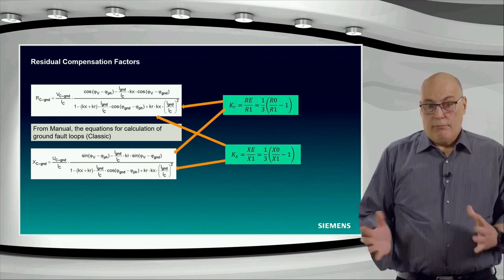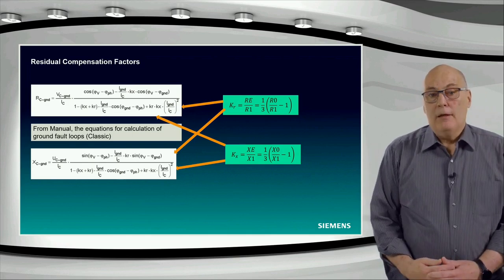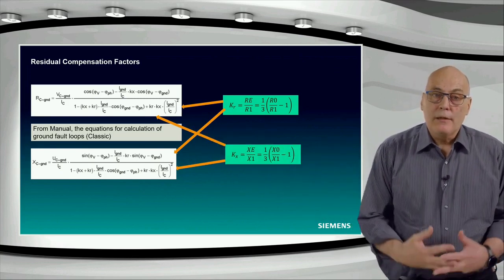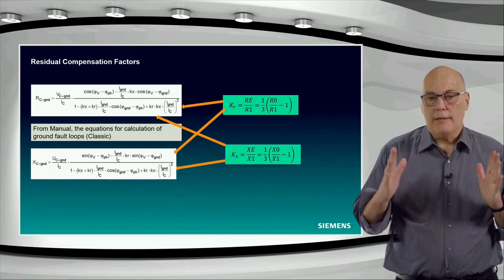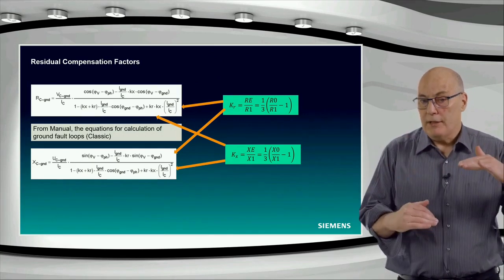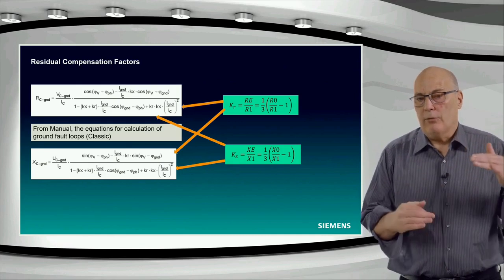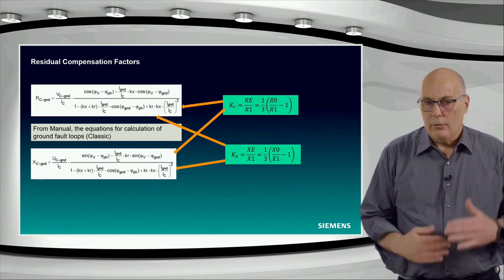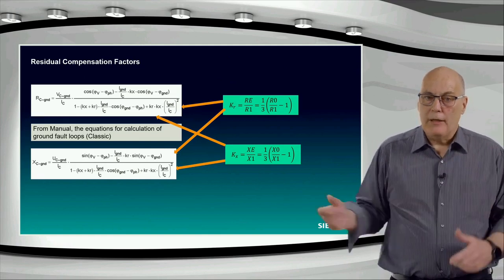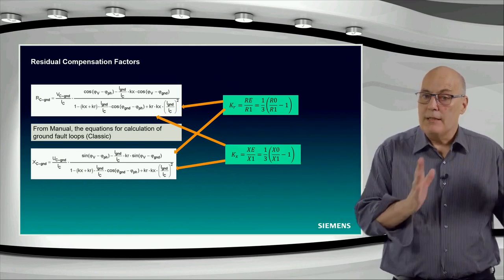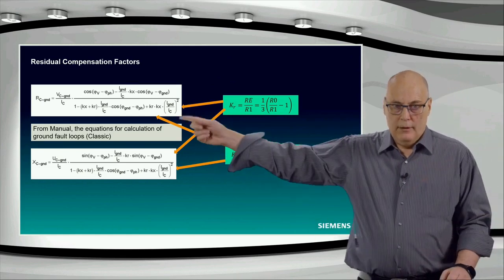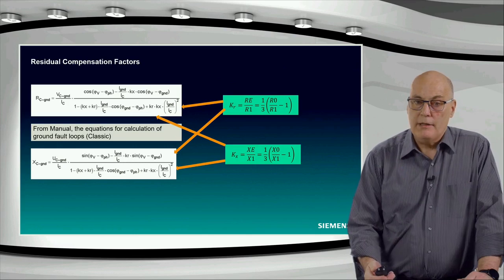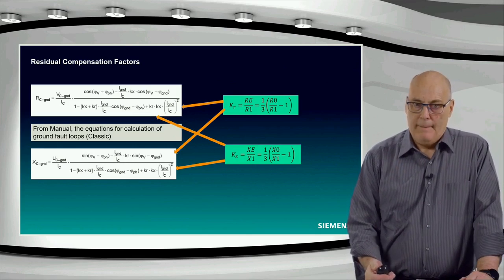Why do you use this rather intricate method? Because on the left-hand side of these 2 equations, the measured impedance is the positive sequence impedance. So we can apply the same reach setting. Well, later on, we'll apply reach settings. And we then no longer discuss, is it for a ground fault, is it for a phase-to-phase fault? It doesn't matter, because both the phase-to-phase faults and the phase-to-ground faults will measure an impedance which is basically the same. It is the positive sequence impedance, or as shown here, the loop impedance. And we can therefore apply the reach settings based on positive sequence impedance.